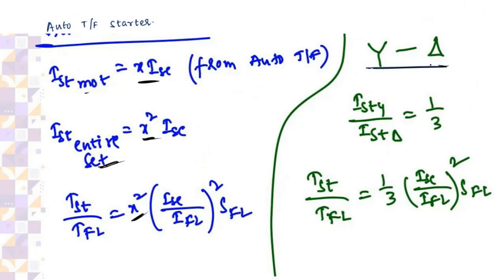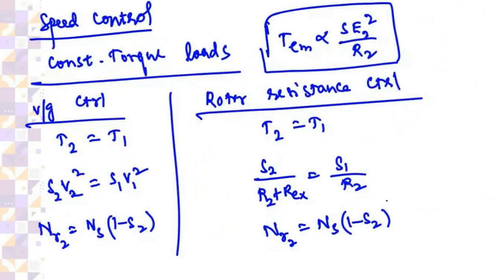And the star delta connection will be like this. The star connection will draw the current compared to the delta connection is 1/3 of delta connection. If you take up only star connection, it will be V by root 3, phase voltage by root 3 times the impedance. So you'll get 1 by root 3 whole square will be 1 by 3. So this comes out as 1/3. Right. So remember the formulas, based on that you may get a question.